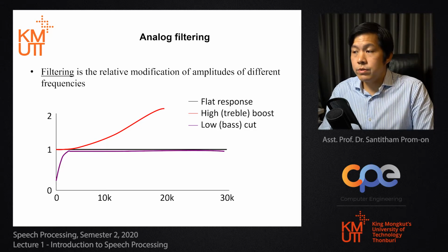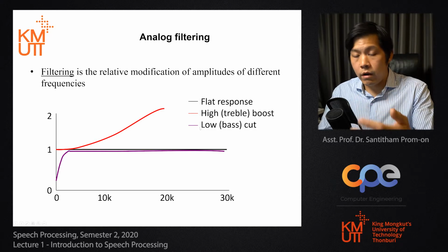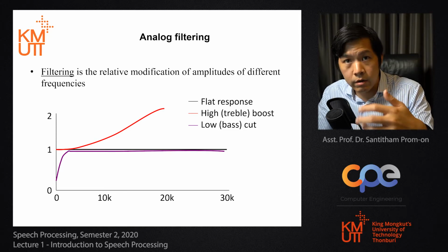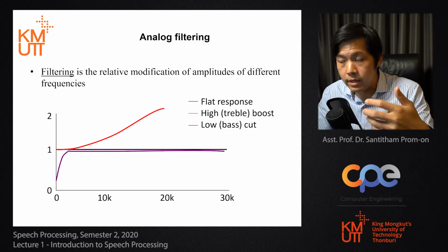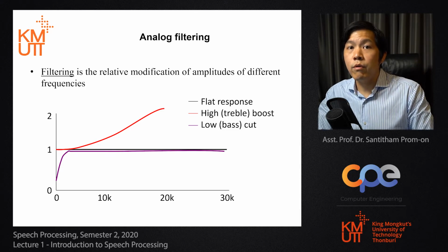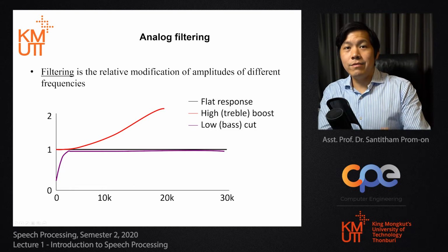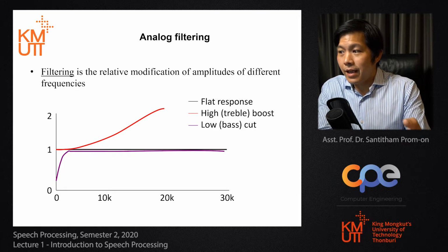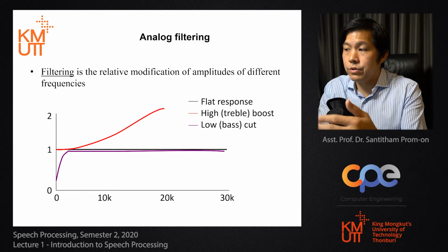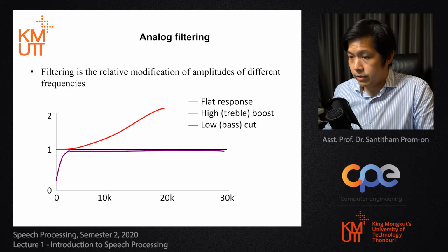It removes the bass from the sound. Why would you want to do that? In audio processing, you may want to remove the bass sound. If, when recording, I speak closer to the mic, there is a proximity effect, and there will be a lot of bass in my sound. Maybe it will be the sound of the saliva in my mouth. So maybe you want to remove those by creating the low bass cut here. Actually, some types of microphone contain this type of filter that allows you to select which frequency response you want from the microphone that it records.